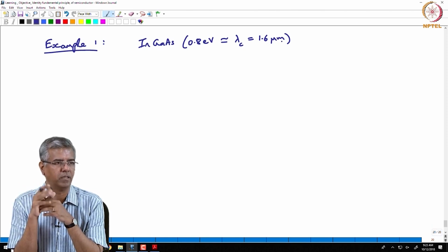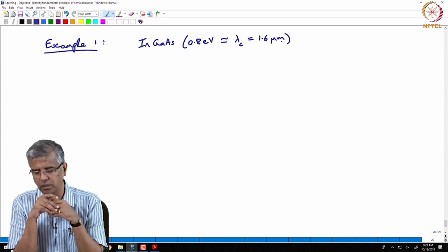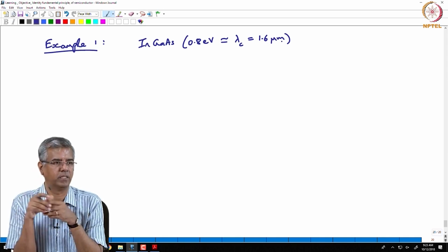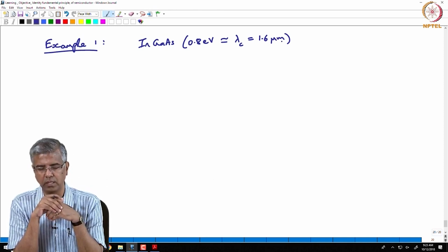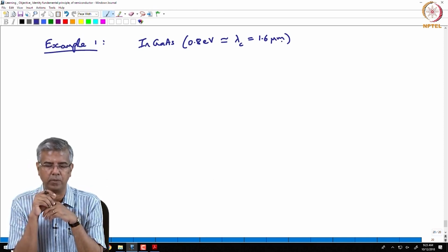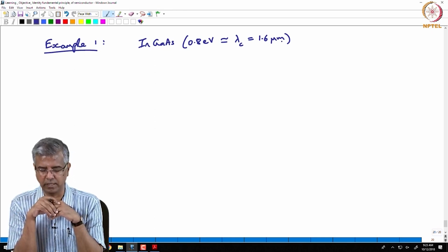1550 nanometers, right, 1.55 microns. So, we needed detectors for optical communication. Indium gallium arsenide was actually proposed as one of those detectors. I should also mention that germanium is another popular detector, not as popular as indium gallium arsenide these days, but